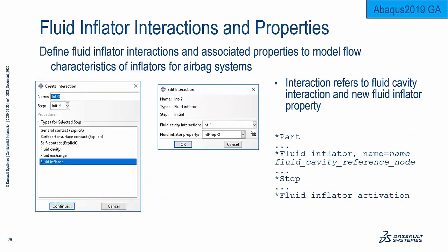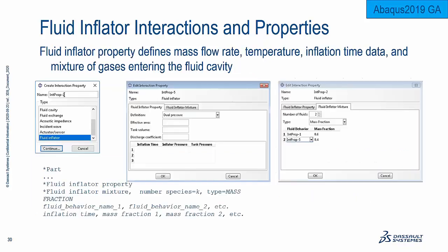Of course, in order for airbags to deploy, you have to be able to pump mass, in this case the mass of gas or fluid, into the airbag. Hence we've incorporated inflator elements or inflators into our methodologies. All of these were available as keyword edits in the past, but as of last year, all of this methodology for developing inflators was made available as part of the Abaqus CAE GUI.